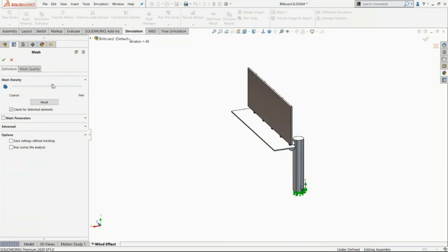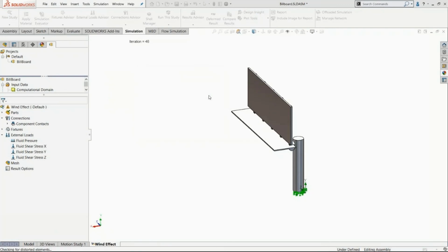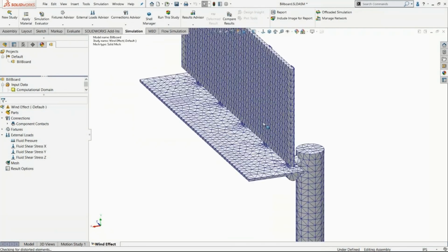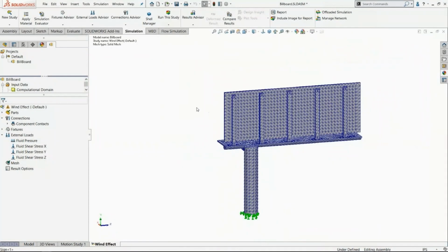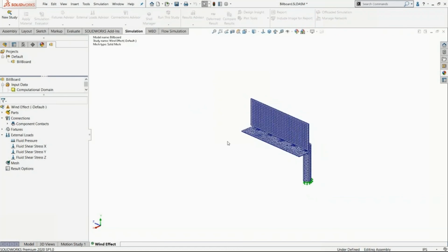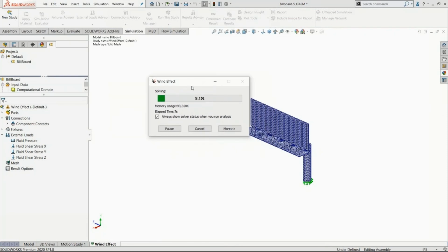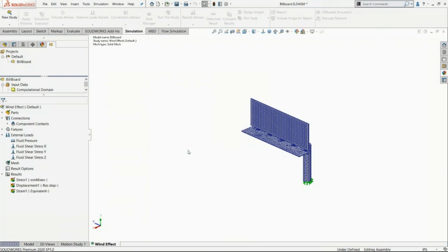Finally, now let's pre-process. In the pre-process stage, we will mesh our model with cubic elements or tetrahedral elements. As you can see, these elements will be solved for the stress equation, or Newton's second law of motion, that the sum of external forces equals K, which means stiffness, multiplied by displacement, or X, the deformation occurring due to these external forces.